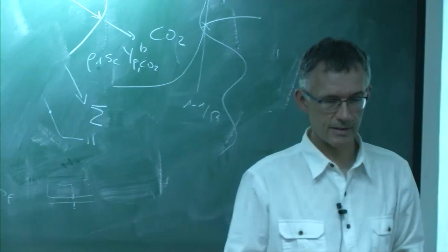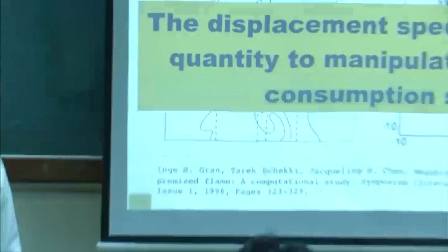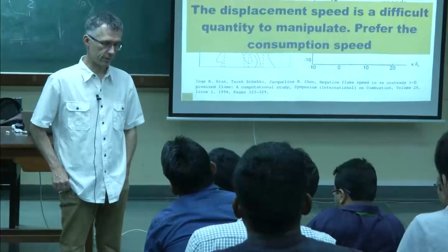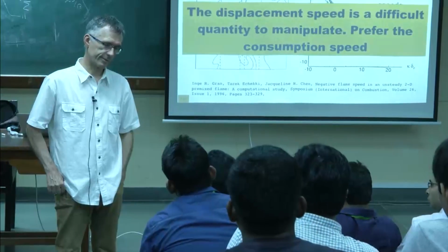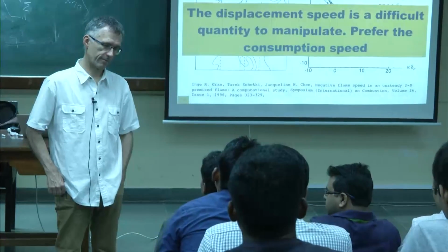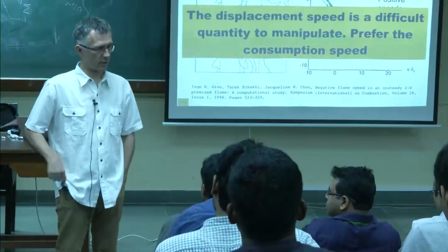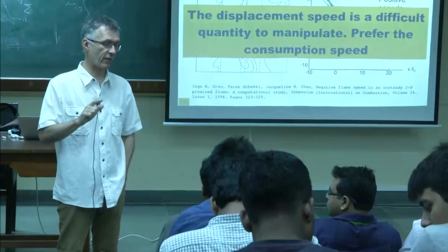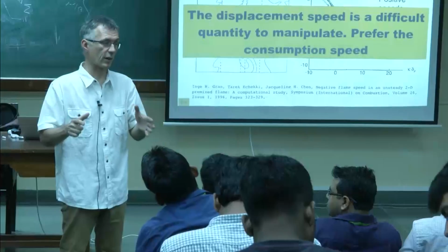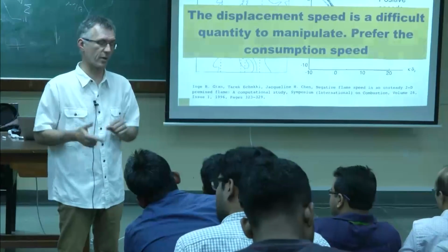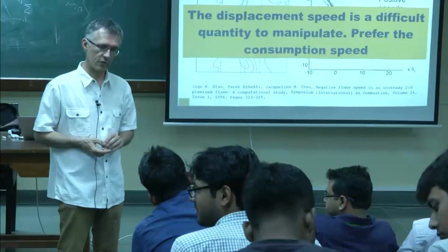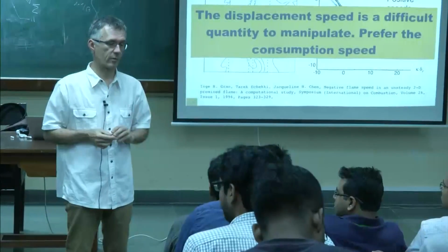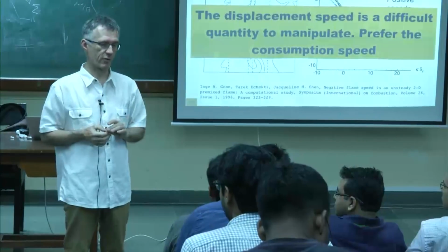Yes? So when we write the governing equations, all the equations were written in the laboratory frame of reference. Yeah, sure. But then in the continuity equation, we were switching the frame of reference. We can do that if it's a constant velocity frame of reference. It's still valid. The equations are valid as long as the frame of reference moves at a constant speed. Newtonian approximation, it's the same equations. So even the momentum equations? Oh yeah, it's the same, as long as it's a constant speed. If the speed would be changing, then it wouldn't work. But if the speed is constant, we can work in any frame of reference. It's still the same equations.